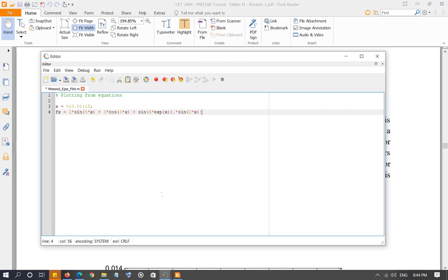Now in the plot you can also write down what is the x-axis, what is the y-axis. You can write down the title of the plot, and many other things that are explained in the tutorial. So to give a label of x-axis, the command is xlabel, and anything that you want to label has to be in quotations, in apostrophes.